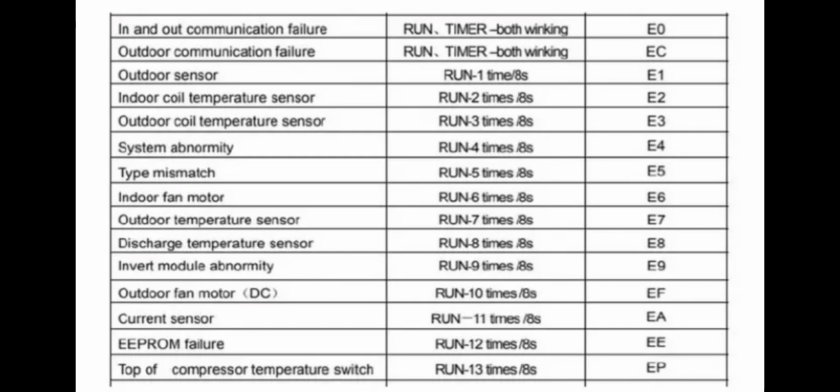E9 is inverter module abnormality or intelligent power module of drive and module fault. Most likely you need to replace the intelligent power module board. Then we have EF, which is outdoor fan motor fault. Check the motor and if needed replace it.